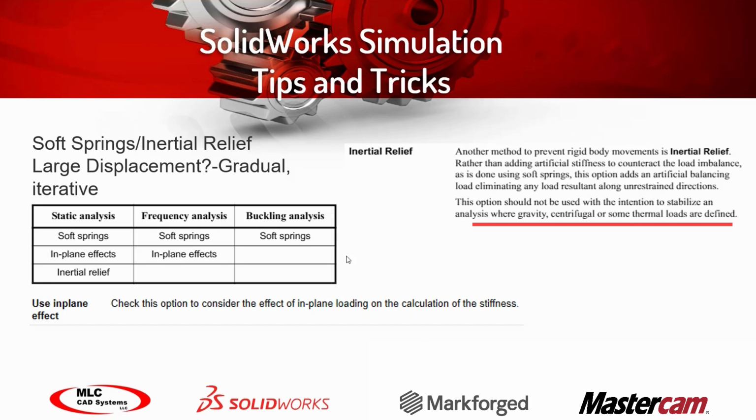But in that, we also go over self-supporting loads where we don't actually have any fixtures. Some ways to use that would be either soft springs or inertial release. Now, if you're using inertial release, make sure you do not use that in conjunction with any kind of gravity load, centrifugal, or thermal loads, because inertia will be affected by that inertial relief. So your results would not be valid. So just keep that in mind. If you have that scenario, go ahead and use soft springs.